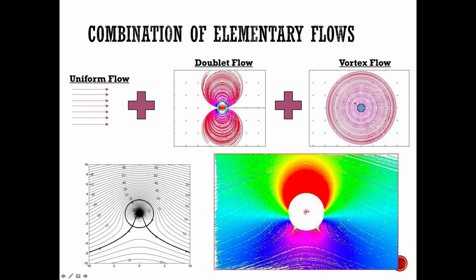Because, remember how we talked about how you can think of a combination of a vortex and the free stream as a phenomenon that produces lift, right? The same concept we discussed when we talked about bound vortex, right? So if you superimpose free stream onto a vortex flow, in a vortex flow the streamlines are going in a given direction, say clockwise.